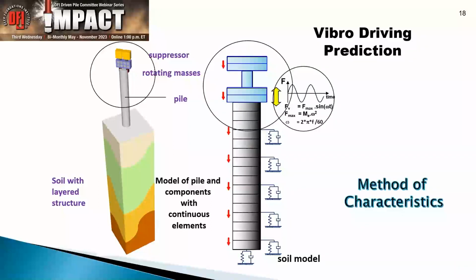This is, by the way, a very important thing when you do, at least in my opinion, pile driving simulations: use the same algorithm, the same method to calculate the outcome of that simulation as you would use later on with your pile driving analysis. If you use the method of characteristics, you can use it throughout, and that means that you can utilize the data, the outcome that you have from your signal matching or from your analysis, again in other simulations, and that is very advantageous.